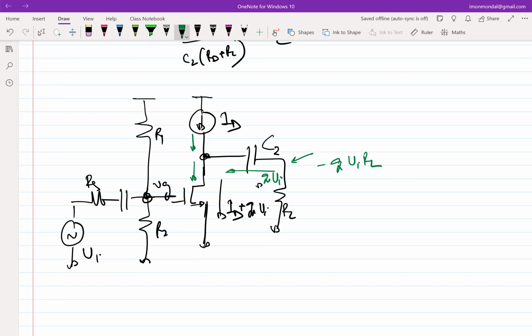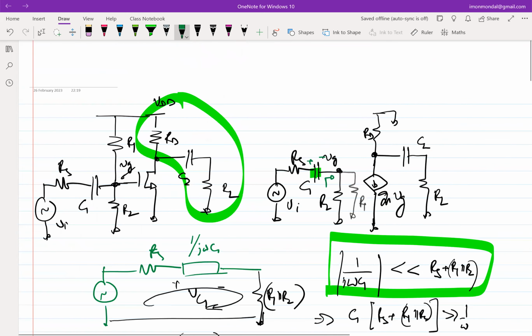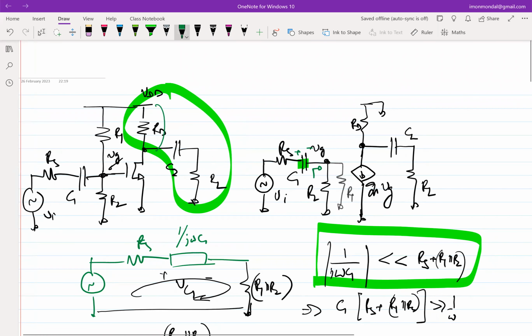Okay, why don't you tell me what was the use of the RD before? If I didn't have an RD, let's assume that we didn't know how the capacitor was, your current source was a solution. Output voltage. Exactly, right? So if the RD was not there, and let's assume the RD was shorted to VDD, then all the incremental current would have flown into that VDD. It's an incremental ground, no change, right? So the output would have been steady at 0, right?